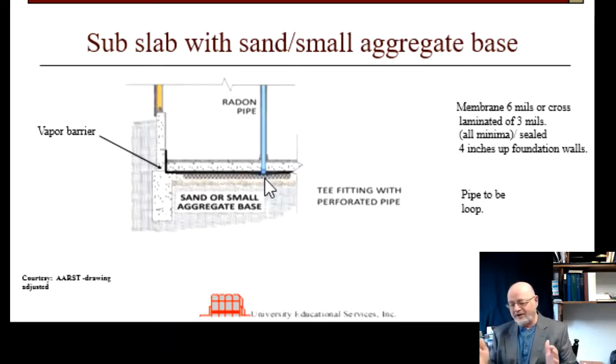Now you're going to put it in about a foot and a half inside the foundation perimeter, approximately, and run it all the way around. And you're also going to put it in a trench. And I'm going to talk about the trench in just a second. So there's a little more effort when you're not using a good gravel aggregate.